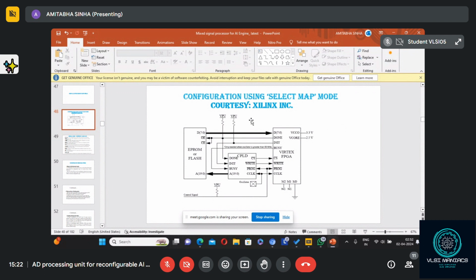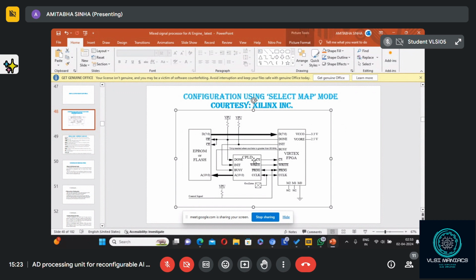Or if it is 0, 0, nothing. 0, 1 means download the bit streams. 1, 0 means a command to execute. 1, 1 means nothing. So let's say this kind of command has been given by the CPU to the CPLD. Then the CPLD will do what? It will send a CS bar signal low so that the FPGA should be ready. The chip will be selected. It should send a write bar signal low.